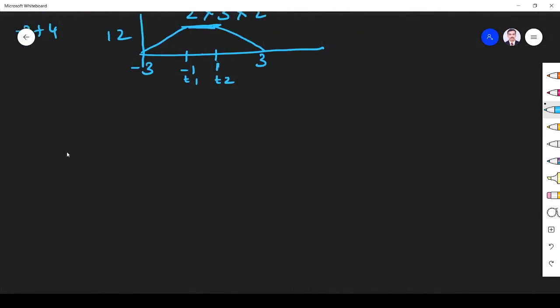Another thing we must know, which they mainly ask, is what is the convolution between e power minus at star e power minus at. That is given by t into e power minus at. This is one of the important problems, and we must remember it.